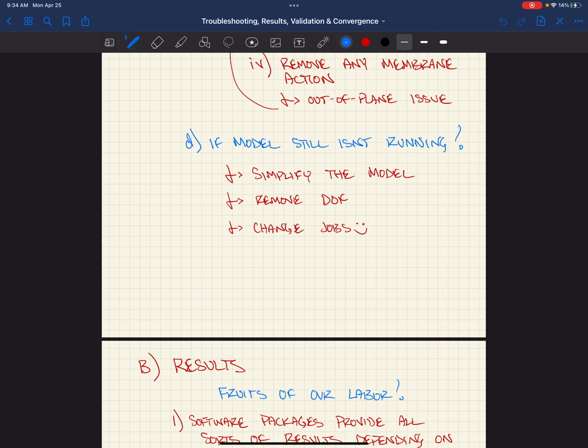But in Revit, as I mentioned, the analytical model, or their mathematical model, is based on the center line of members. So if you have a W18x35 and then it frames into a W18x40, those things are a little bit deeper, right? And so the real center line of that member is a little bit lower than the one that's coming in next to it. And if Revit doesn't assume that they connect, then it's going to create another node at the end of this member when it kicks it to VA. And that's what happened all over the place.